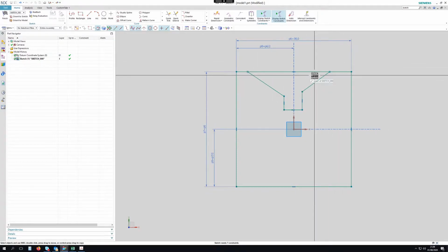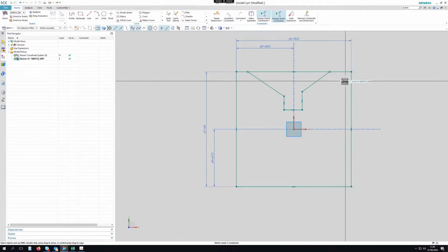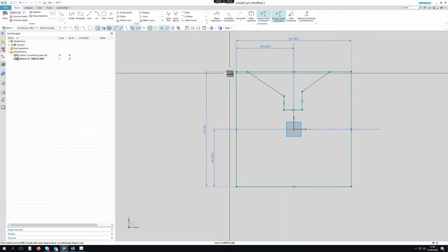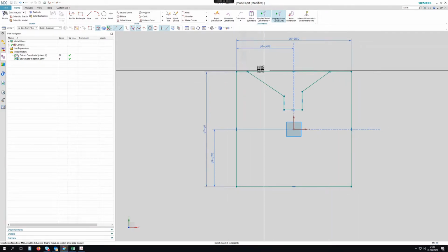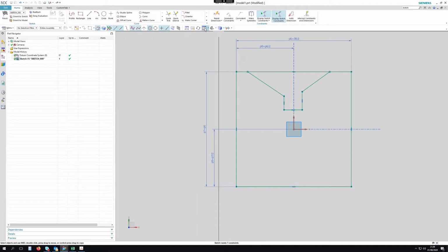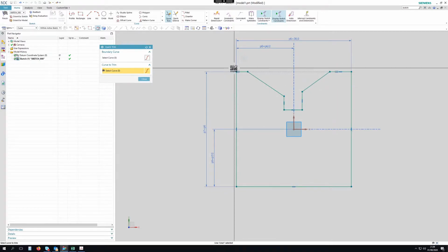I'm going to chop this piece out of the middle, and by default the system, because this was a single line, will make sure that this side of the line and this side of the line are always in line by adding a collinear constraint after the fact, after I've cut this piece out of the middle. So let's trim it out, quick trim, it's one click, it's gone, and there's the extra constraint it's put on for us.